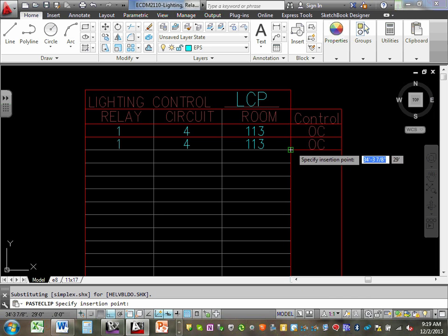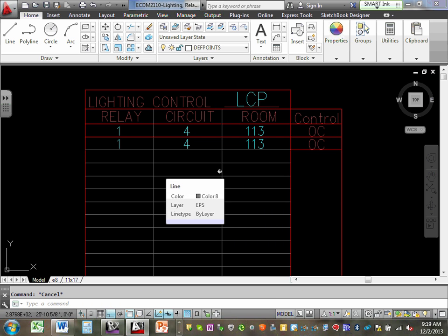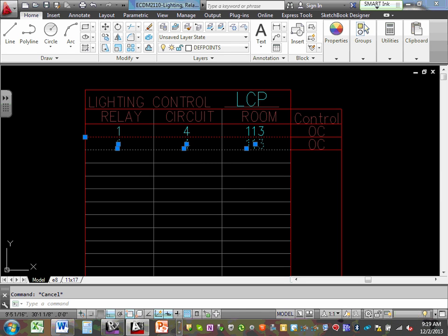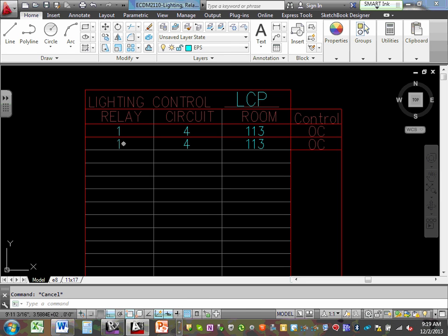So what I'm trying to do, guys, is make another line exactly the same. Copy with a paste point, click them in. Now let's go modify them. I'm going to go to Revit. Now the second room that I'm going to have, this room, it's circuit number 4 and occupancy sensor, right? In the second bathroom, circuit number 4, occupancy sensor. Okay, so this is relay, then click on that text, guys.